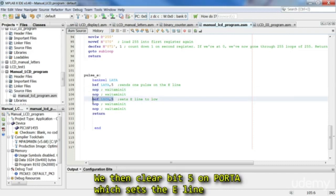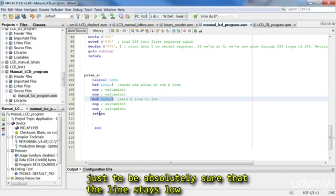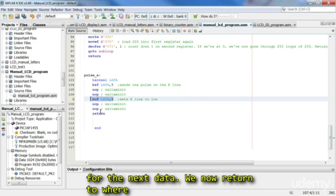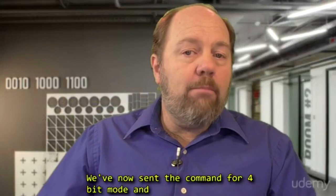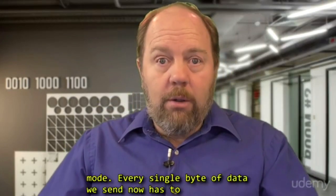We then clear bit 5 on latch A, on port A register, which sets the E line to low. We wait around for a few more clock cycles just to be absolutely sure that the line stays low long enough for the LCD driver chips to get ready for the next data. We now return to where we left off. We've now sent the command for 4-bit mode and pulsed the E line. So now the display is in 4-bit mode.